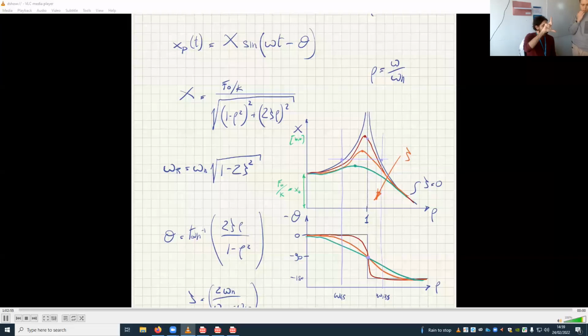So it's from minimum. 0 means no sinusoid, no sine wave. Sigma range of 0 means constant stress. But is it from here to here? In fact, the stress range is this, from here to here. So it's not from 0 to maximum, it's from minimum to maximum.